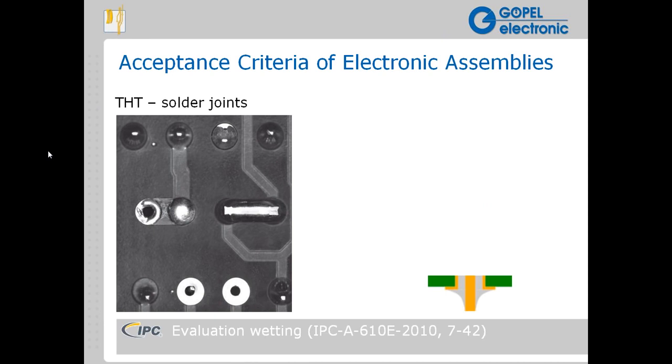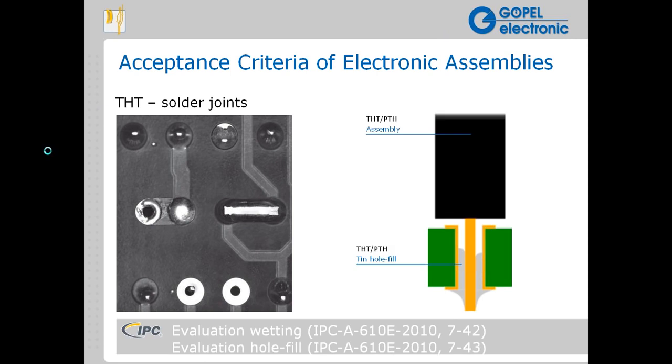And again, we can characterize some of the failures in through-hole assembly with AOI. If we look at a case like this particular connector, we can take a look at the pins themselves. Are the pins deflected? Are they out of place? Are they in place? We can see that with AOI. We can look at the bottom side of the board, and we can look at the solder joint as it exists on the surface and look at the nature of that particular solder joint.